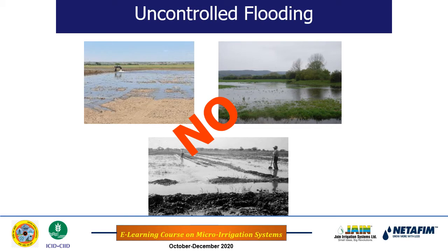And as I told you earlier as well, in surface irrigation method we follow this by allowing the water to move over the land surface. When water moves over land surface, some of the water infiltrates into the soil, stored into the root zone. Some of the water may deep percolate beyond the root zone, and some of the water moves of course over the land surface. And while this water moves over the land surface, the water will also be stored in the root zone in the next piece of land actually. So this is surface